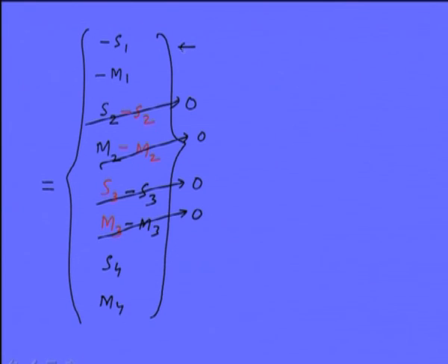At these two locations, which are the shaft ends, because it is supported, that is simply supports are there, this will be having shear force and bending moment. It depends upon the end condition, because while development of the element we don't consider the boundary condition. So now we assembled all the three elements. Now the need is to find out what the boundary conditions are and apply them suitably. So let us see now the boundary conditions.